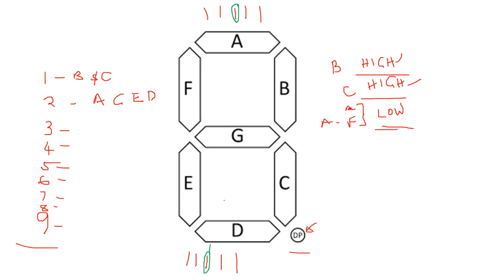It doesn't really matter. The only thing we make sure of is that, as usual, you use a resistor so that they don't burn. These are very, very small LEDs. Remember, because they are just LEDs, you have to protect them. You have to use a limiting resistor to limit some of the current from burning them. So it is important you check on that.